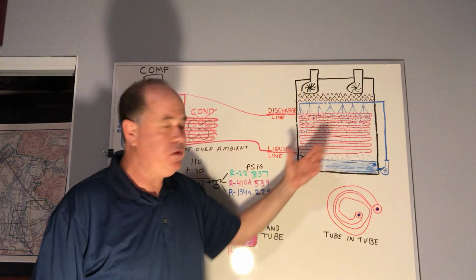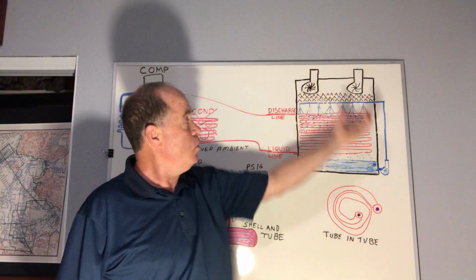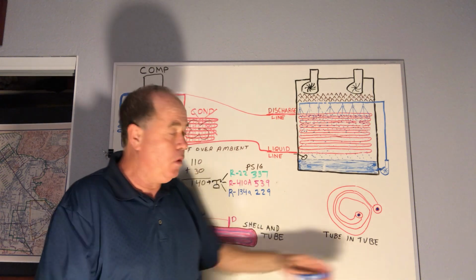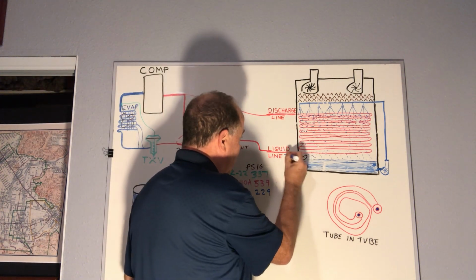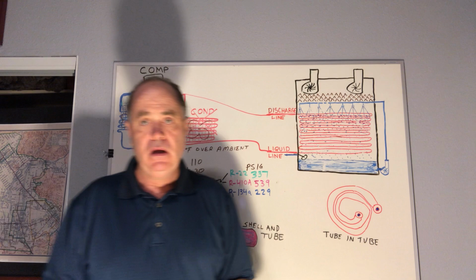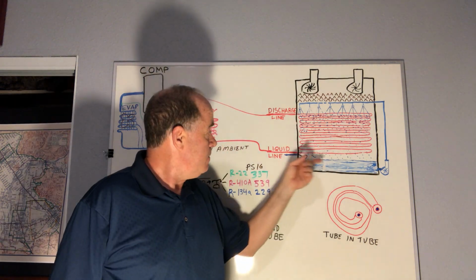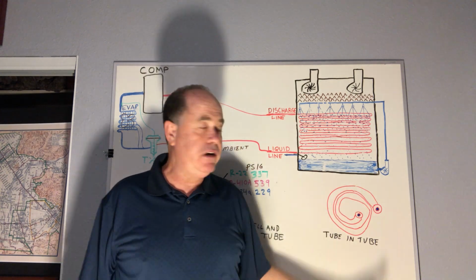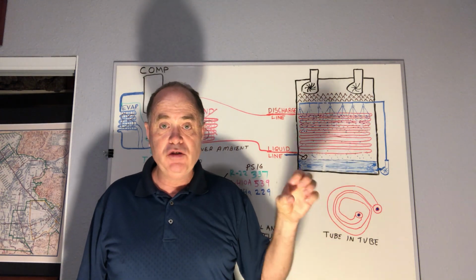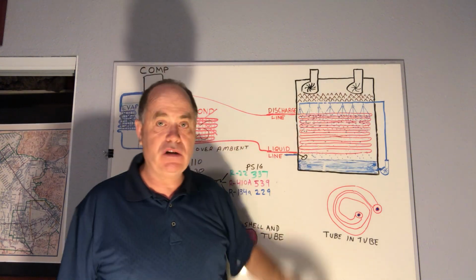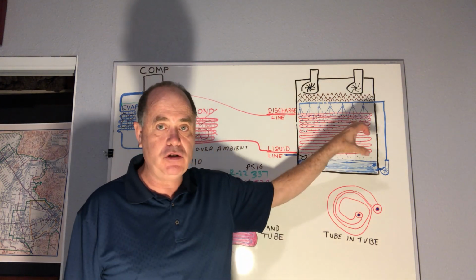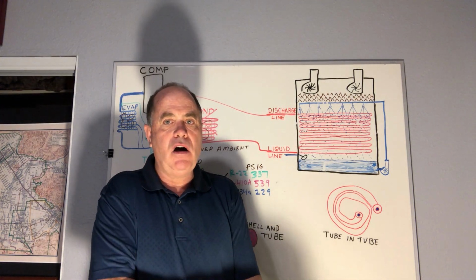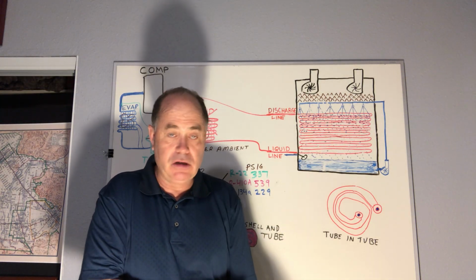The same thing happens with a cooling tower and evaporative condenser. When all this water evaporates, the minerals that were in the water coming in to the tower, which has minerals in it from the city, the concentration of it goes up. The greater the concentration of minerals, the more likely those minerals are to stick to your condenser tubes, the warm condenser tubes, insulating them, which is called scale. And we don't want scale on our water-cooled condensers.